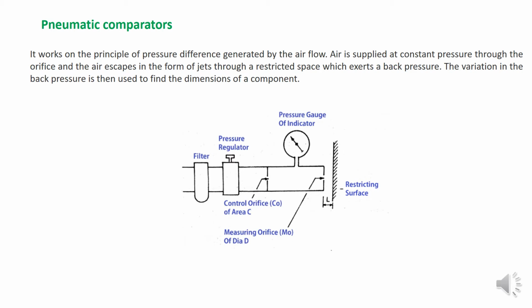Pneumatic comparators work on the principle of pressure difference generated by airflow. As the name says, the working medium we use is air. Air is supplied at constant pressure through an orifice, and the air escapes in the form of a jet through a restricted space, which exerts a back pressure. In this image we can see